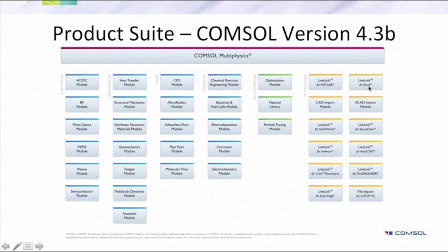For example, imagine you have your model in Excel. Via the live link, you connect the two programs together. You work in Excel. You take control of COMSOL via Excel. You can parameterize your model, which communicates with COMSOL. The model is solved, and you have everything in one environment.